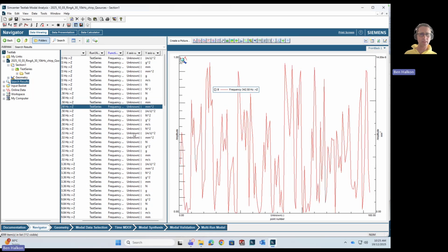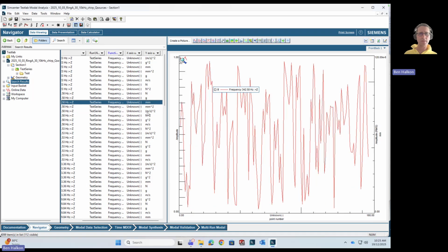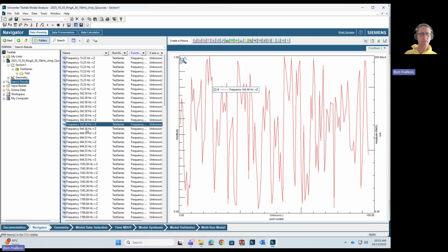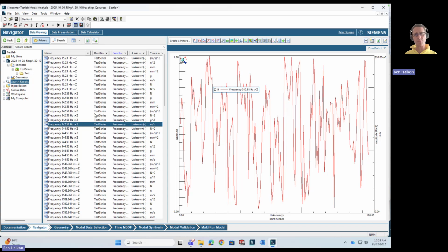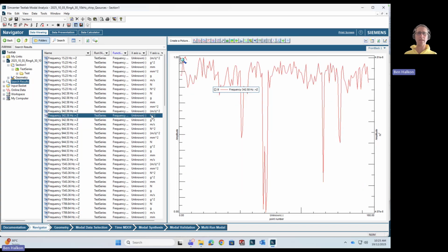So that's a PSD, there's a millimeter per second squared, millimeter squared. Now there's obviously a velocity function there, so various different processed parameters for the measurement made by the laser vibrometer, and at the same time the measurement of the reference force transducer integrated within the lightweight shaker. So that all looks reasonably promising.